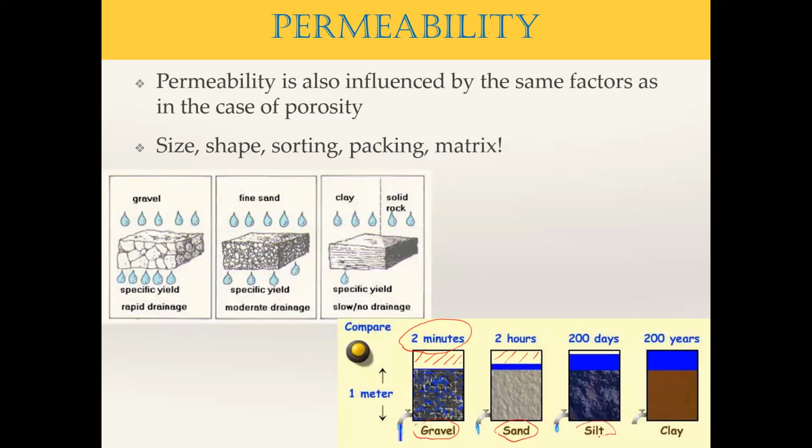If you consider the silt, this is after 200 days. You can see only a very small amount has drained out. Clay, this is after 200 years. So the water movement is quite small. But yes, it can store a very large amount of water. So this is a good figure for you to understand the hydraulic conductivity, how it changes for different formations.